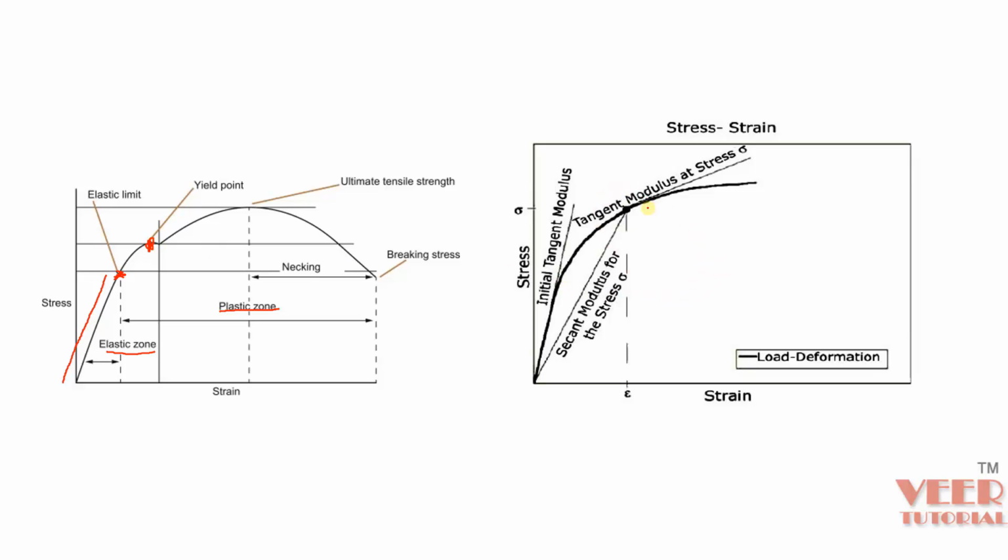When we want to define the plasticity, we have multiple options. We can define different points for this curve, or we can define what is called the tangent modulus. Tangent modulus is basically the slope of this curve at the point of yielding, the point from which the plasticity starts. You can find all the details about this in any book of material science. I'm just going to give you a basic overview. Now let's go to LS DYNA and define the material properties.